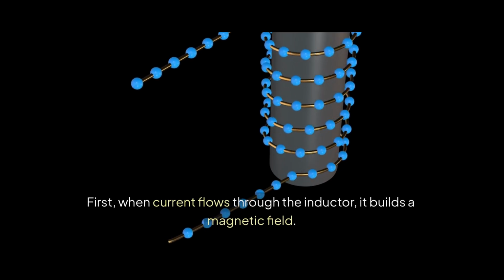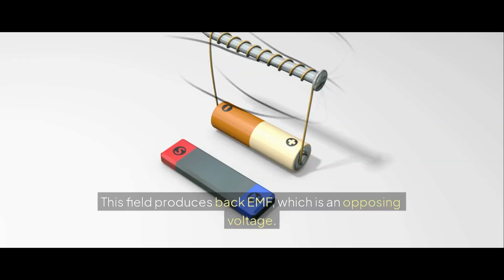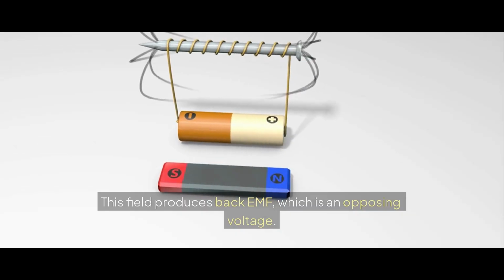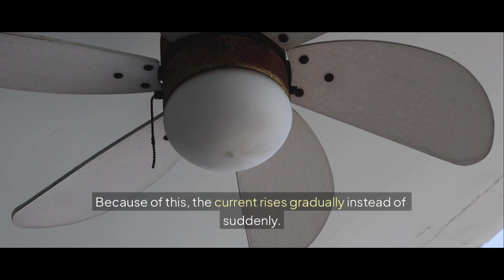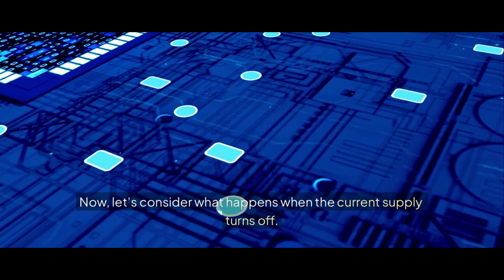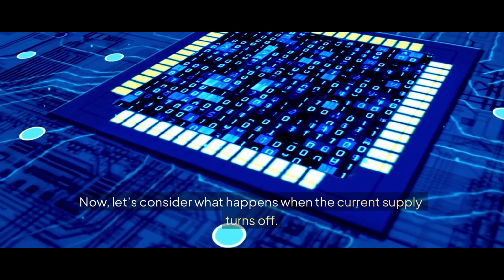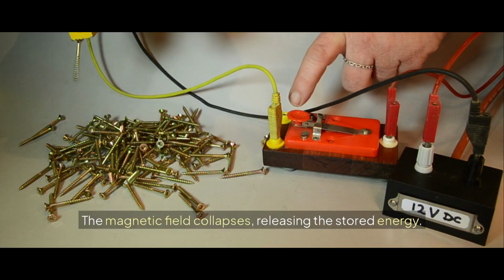First, when current flows through the inductor, it builds a magnetic field. This field produces back EMF, which is an opposing voltage. Because of this, the current rises gradually instead of suddenly. Now, let's consider what happens when the current supply turns off. The magnetic field collapses, releasing the stored energy.